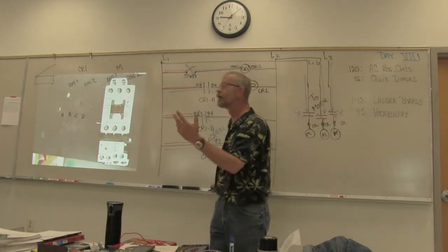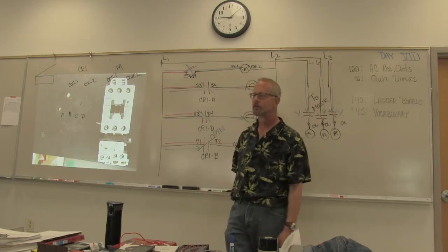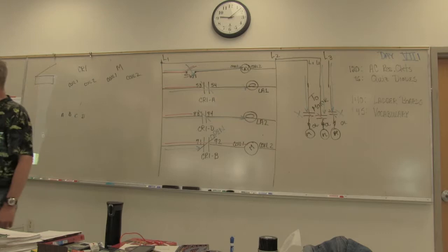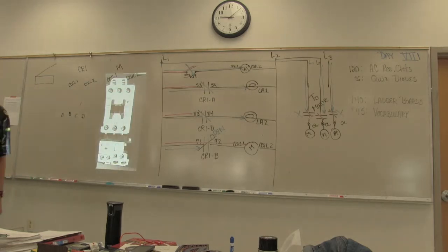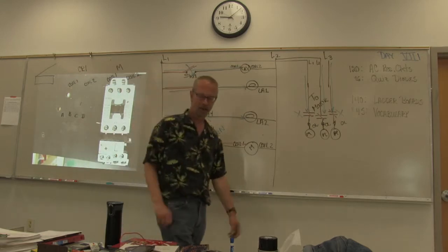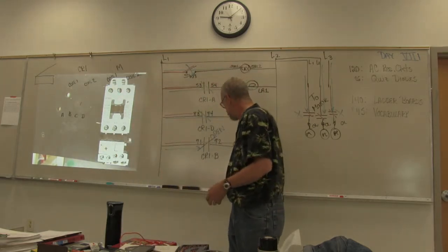So what is it really? Just a big switch. It's a big remote-controlled switch where we can take a very small amount of energy and control the coil and use larger amounts of energy remotely on the other side of the firewall. Okay?